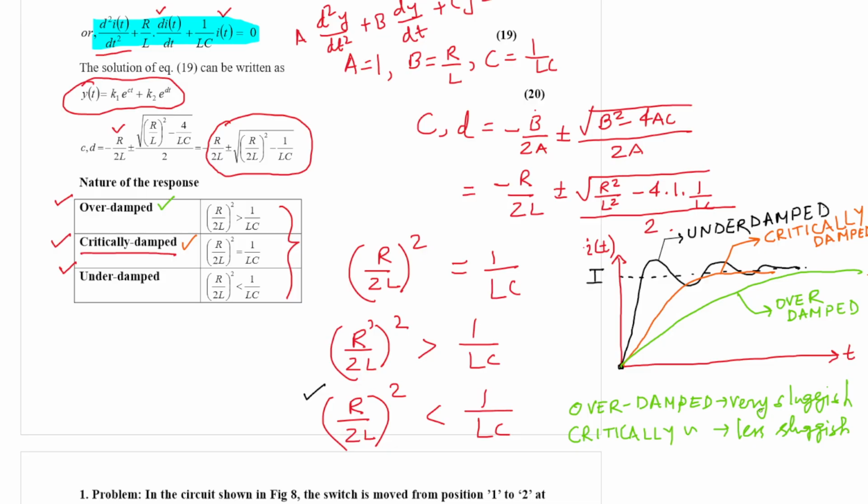However, in the first case, the underdamped case, it will get around the same value, but you will observe this is overshoot, this is called overshoot. This spike, this is called undershoot. You will observe a lot of these issues, and you will see that the response settles down after some point of time. This is the nature of the underdamped case.